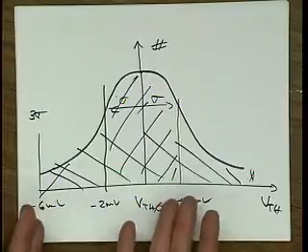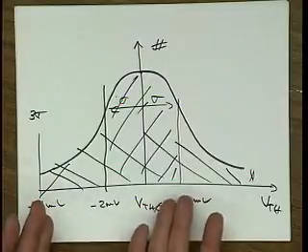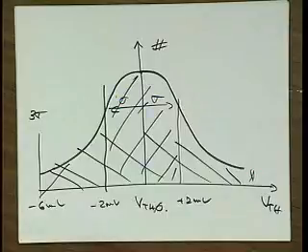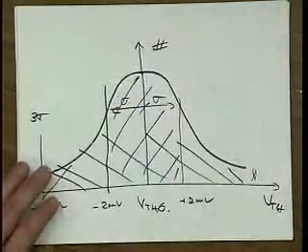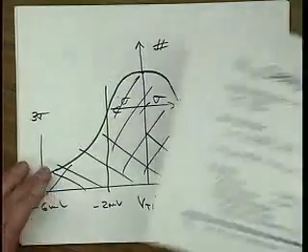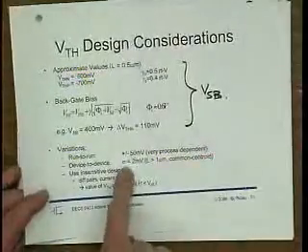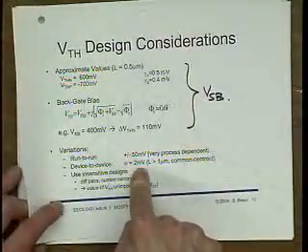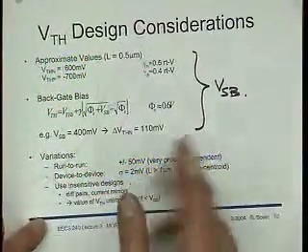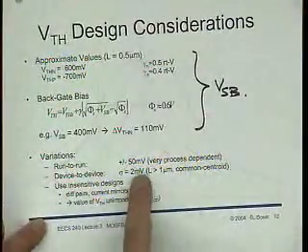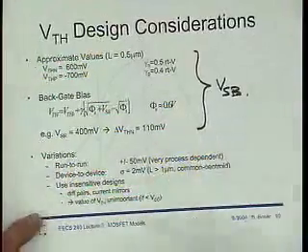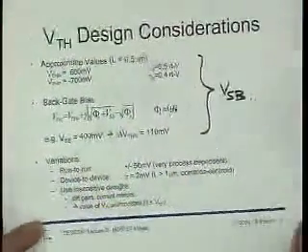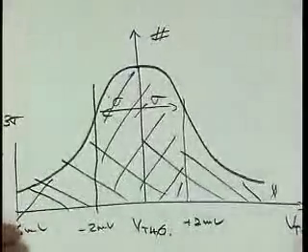Then we actually have a chance to make a bunch of ICs where a fair number of them actually meet our constraint. We've got to be a little bit careful when manufacturers or whoever quote these sigma numbers. Well, the offset variation of our device is not 2 millivolts. It's sort of a majority of the devices within there, but we'll need to multiply this by 3 to get really a good majority of our devices in there.